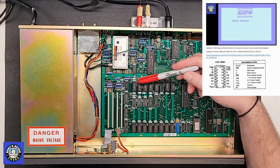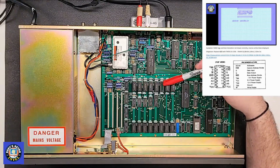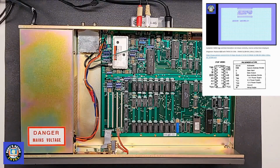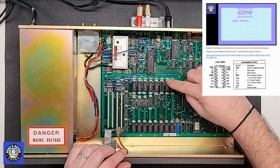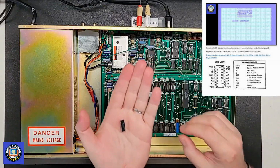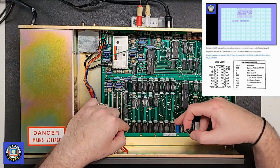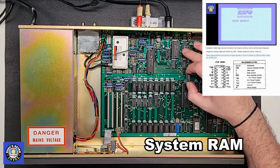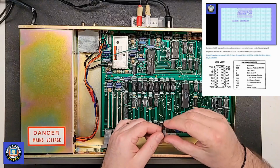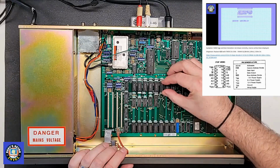And we can find U22. Now this is marked U17, 18, 19, 21, 22. Oh, so we can see what the problem here is. As you can see, I forgot to put back the RAM chip, this one here. While I was doing my testing, I put sockets on the video RAM. I put sockets on the memory RAM. I also socketed the keyboard controller, and I must have forgotten to put this one back. So let's put this one back in here and see if we can get this thing booted up.